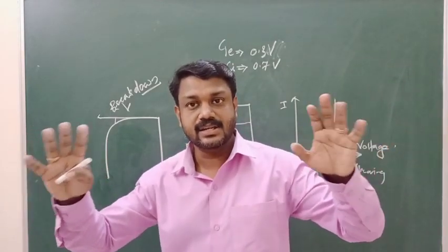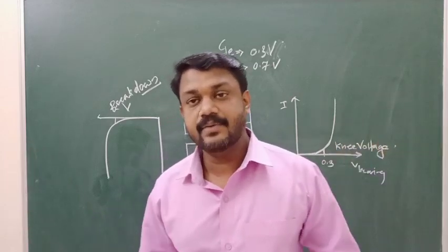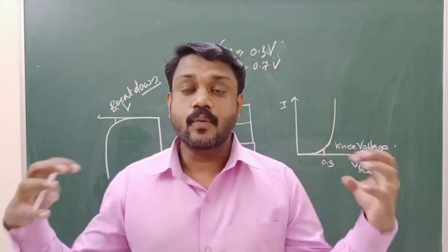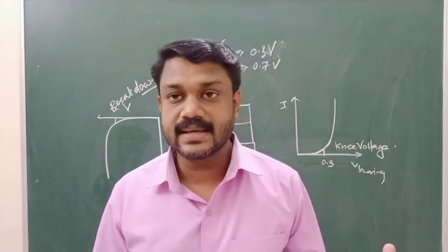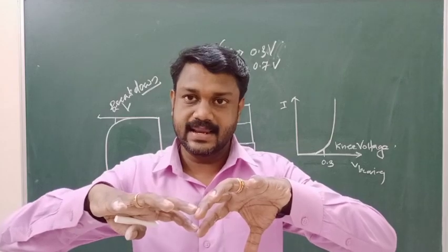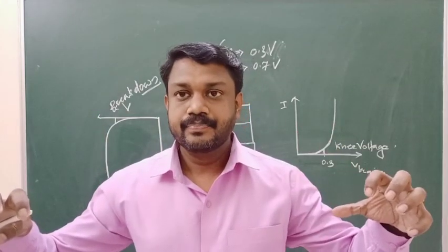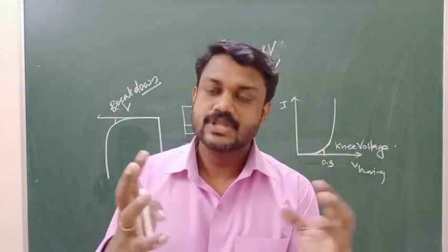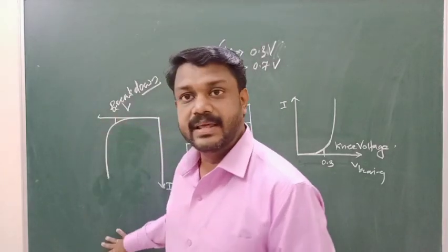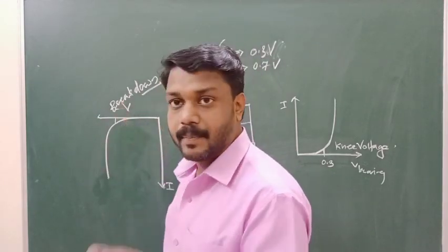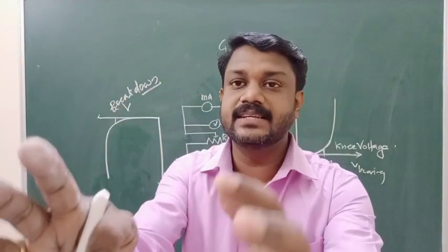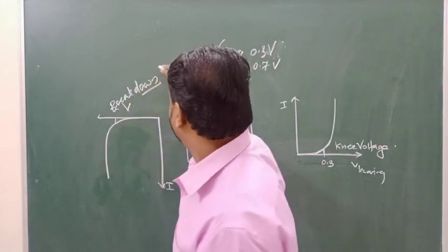It reaches a condition at which the voltage developed across the depletion region is sufficient to break the covalent bond between the minority charge carriers and the opposite charges. So the covalent bond is breaking up. The minority charge carriers become free across the junction, so they will cross the junction with the help of reverse bias. Then the current abruptly increases, and that particular voltage of the biasing potential at which the breakdown of the depletion region happens is known as the breakdown voltage.